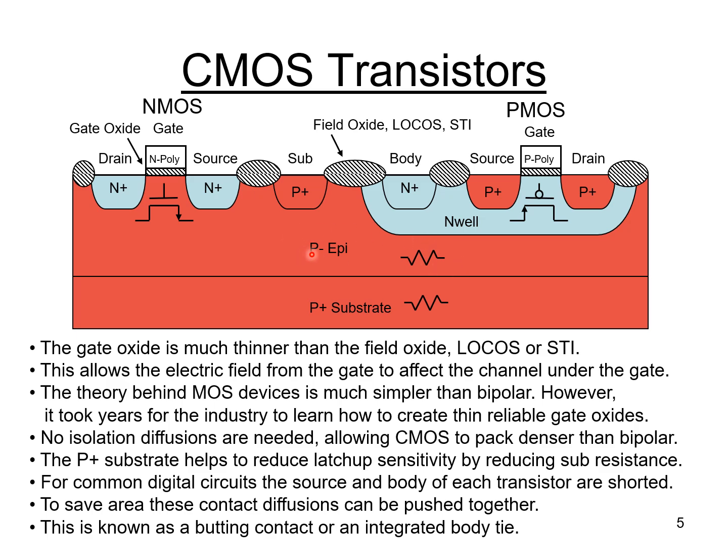You need to put the transistor in a low doped epi region because you need a low doped body region, but you really don't want the substrate to be low doped because that makes latch up very easy. Again, in a later lecture I'll talk about latch up concerns and why you want a highly doped substrate to reduce latch up. But this is how you get that.